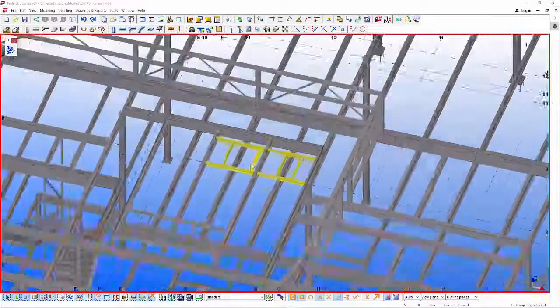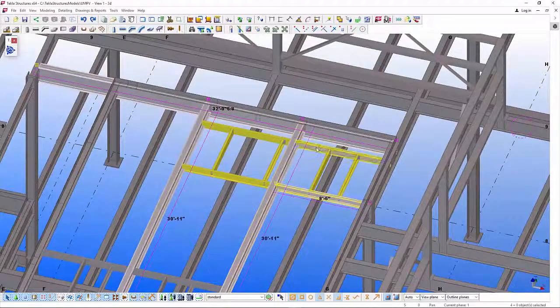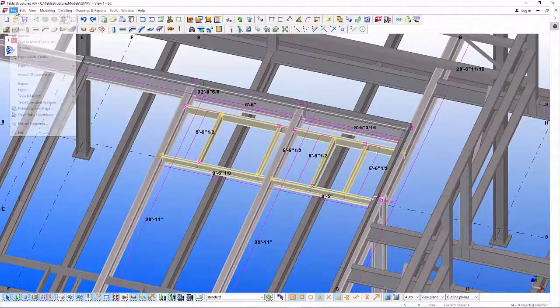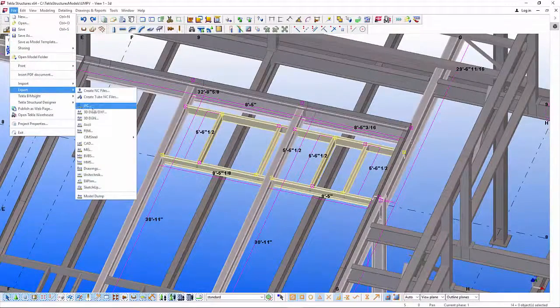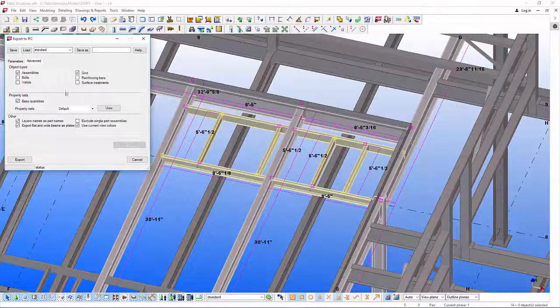Okay, we're going to start here in Untitled Structures, and we're going to go ahead and select all of the objects that are associated to this particular RFI. And then what we'll do is we'll go to Export and IFC. And we're going to do of selected objects. We'll include the property sets that we want, so that way the RFI number is exported in the IFC file.